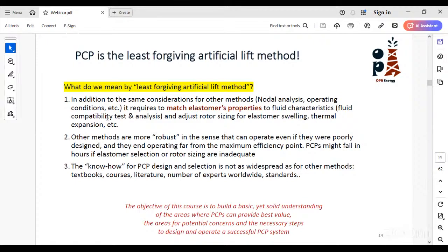If the fluid has a high gas rate, and in this gas there are aromatic components, meaning the rings that we have in benzene, what we call benzene compounds, this highly affects our elastomer and causes it to become brittle with time, and so to be broken. After that, the efficiency of the pump is very bad for producing the fluids that we are targeting.